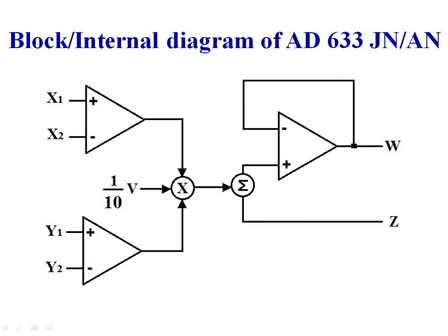Out of the 3 operational amplifiers, 2 operational amplifiers are configured as differential amplifiers and the third operational amplifier is wired as a voltage follower or buffer amplifier.